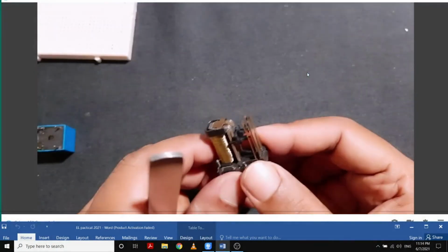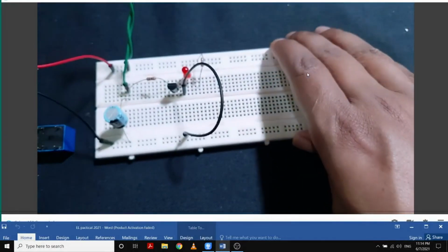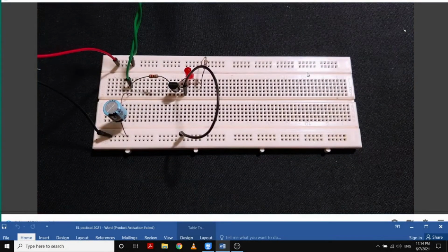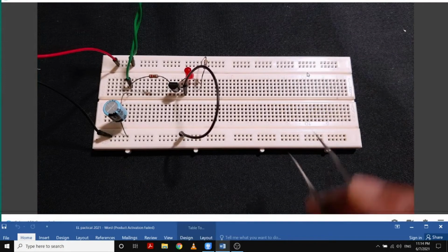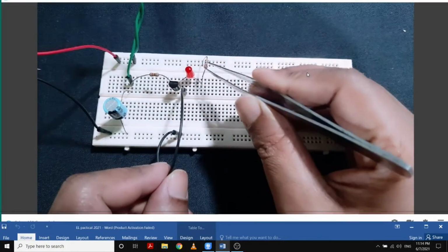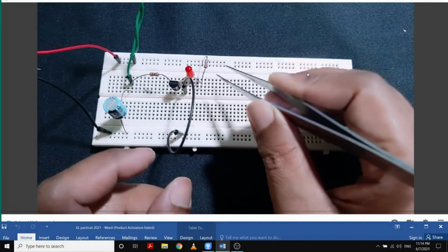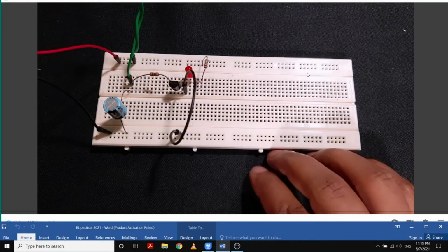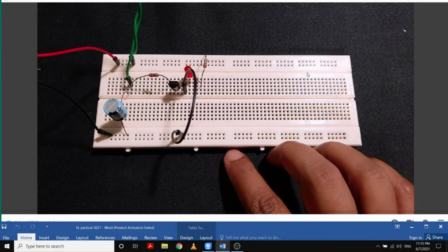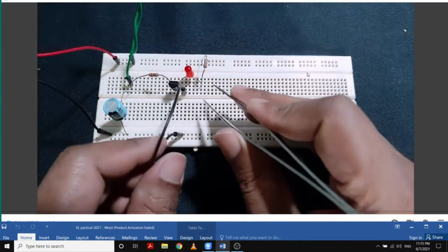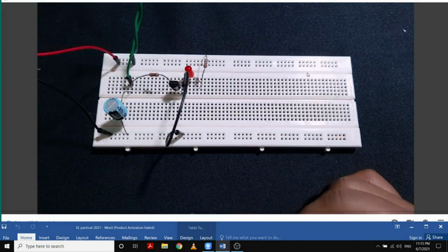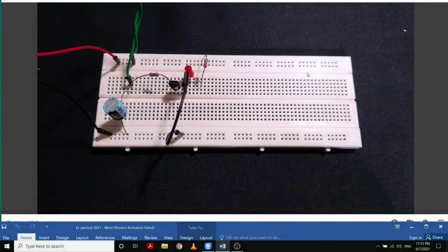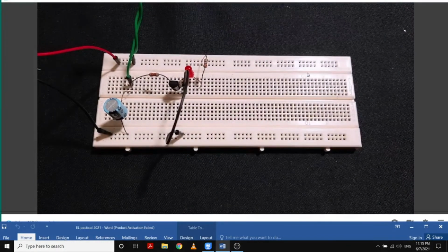Now, you are not advised to use this relay switch to replace this LED bulb and resistor combination, as well as to connect a relay switch with a main electric bulb, right? A main 230 electric bulb. You are not going to do this because it is dangerous. You are practicing that part, but I will connect this and show you how it is done.